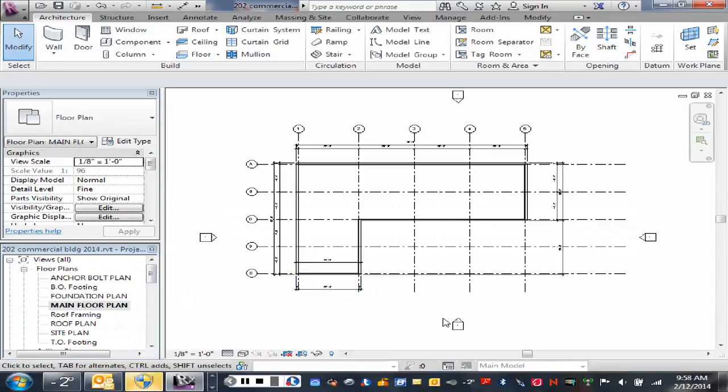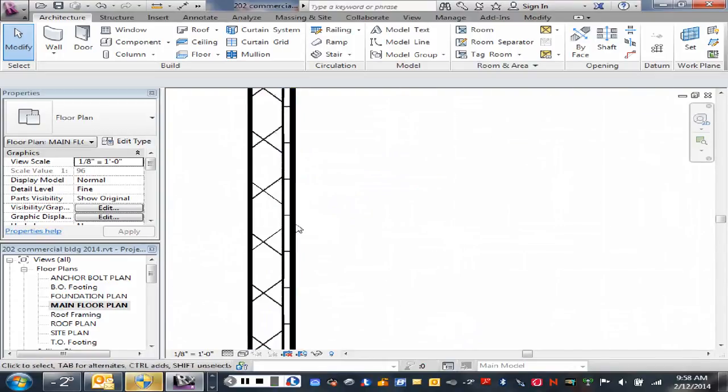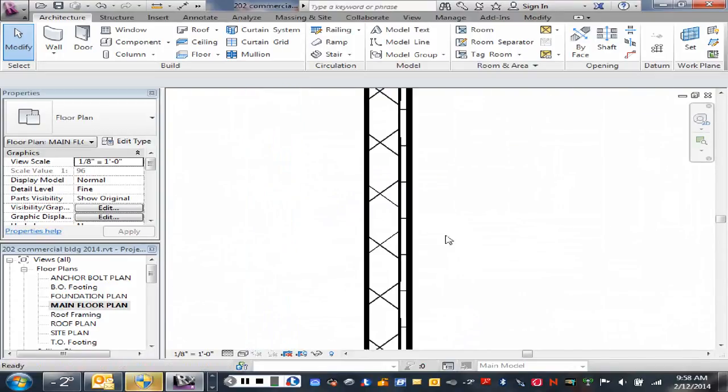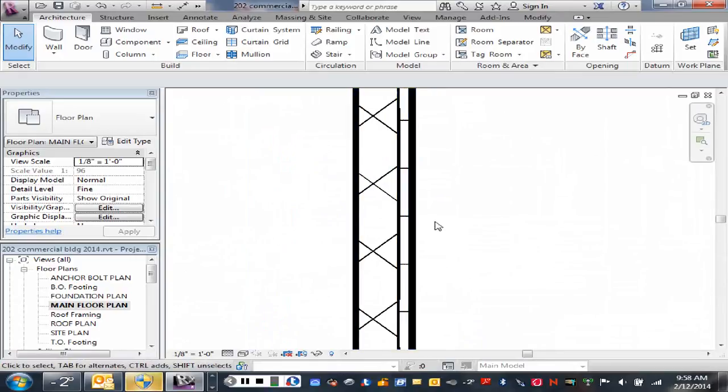And yesterday we talked about that exterior wall and about the columns being in the corners, and what the makeup of the exterior wall was going to be was 8-inch concrete block on the outside, right? Then 2 inches of rigid insulation, and then 5/8 gypsum board on the inside. Did you modify your exterior walls? Okay, so we need to make an adjustment on your basic wall that you threw in to start with.